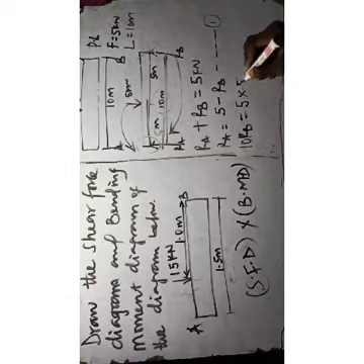So that will be 10 RB clockwise equal to anticlockwise, and 5 is covering how many meters? 5 meters. So that will be 5 times 5. In other words, 10 RB equals 25, so RB equals 25 divided by 10, and RB equals 2.5 kilonewton. So from here you've gotten RB to be 2.5 kilonewton. Therefore you can come here and substitute RB inside here. That will be RA equals 5 minus 2.5, and our answer will be 2.5 kilonewton. So our RA is 2.5, RB is 2.5.